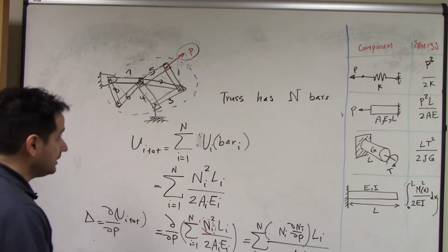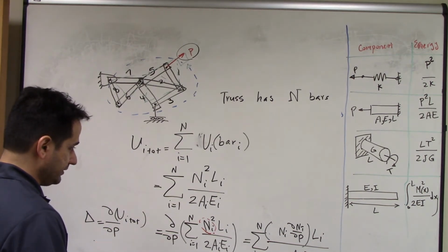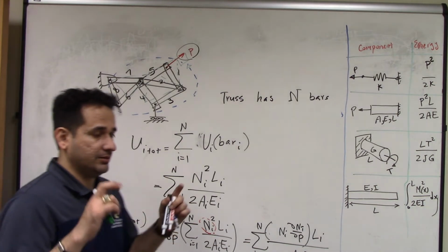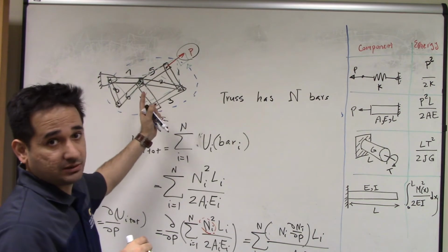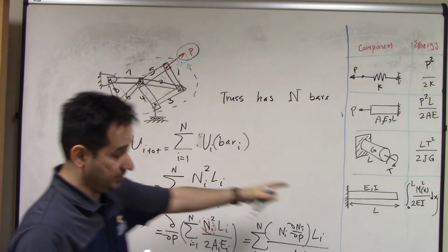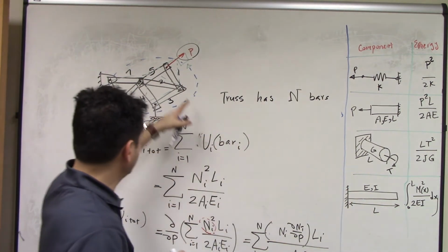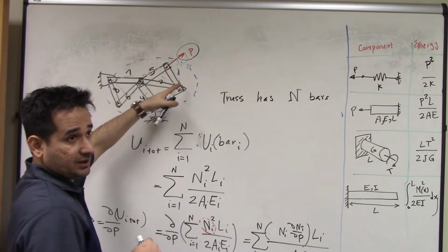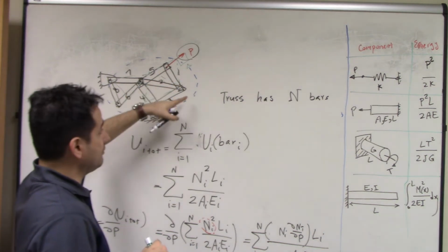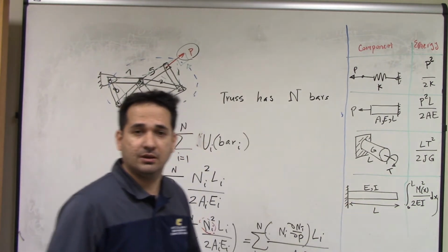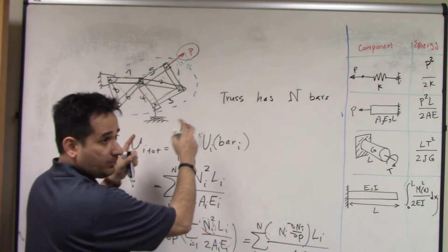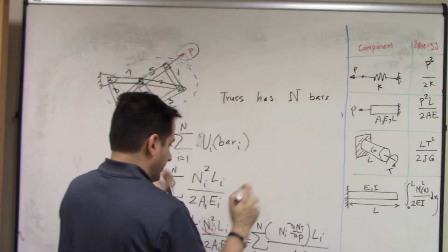So let's write it here. If you have a truss, or in better terminology, a collection of bars, not beams, because this thing is pinned, right? That means that they don't accept shear force. If this was welded, then they would be bars and beams, right? So a collection of bars pinned together, or truss. First thing.